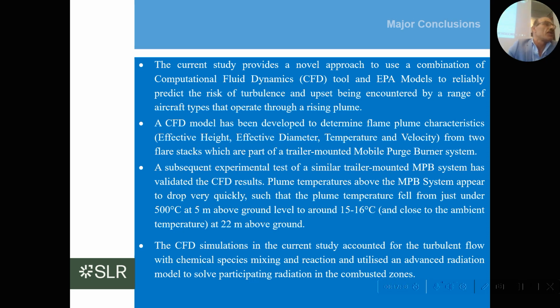In fact, this could be used for any other system. This was only an example. Any other combustion chamber could be modeled using this methodology. A subsequent experimental test of a similar trailer-mounted system has validated the CFD results. In the CFD simulations, the current study accounted for the turbulent flow with chemical reaction, mixing and reaction, and utilized an advanced radiation model to solve participating radiation in the combustion zone.